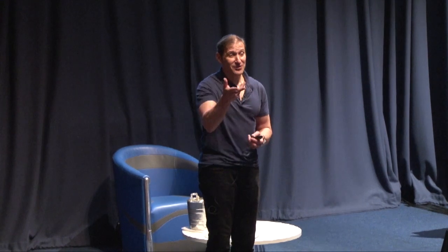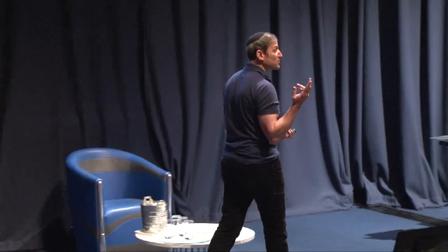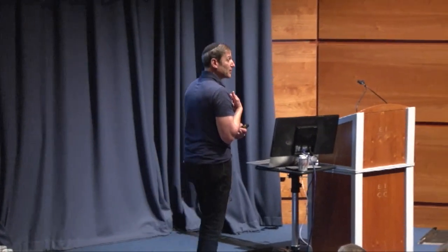And this is most likely, in my opinion, to happen if you put into that patient a superhighway. And for an electron, what would constitute a superhighway? A wire, right? A lead. An electron looks at the lead and it says, compared to anything else I see in front of me inside this human, that piece of metal is going to be a lower resistance pathway for me than this muscle, than fat for sure, than skin, than liver.